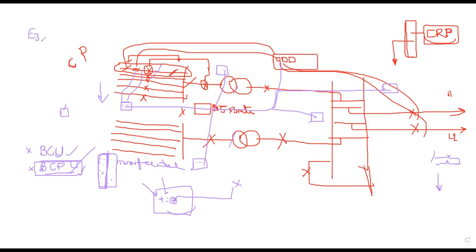If your company has this, you can develop them easily, but most developers give this exercise to the third parties from whom they are purchasing the relays. Suppose I am purchasing the relays from ABB, I will include this in their scope and make them do it. These schemes are again standard, as all the developers have a standard scheme. After developing the scheme, they will provide it to us, and we have to review that scheme in depth.